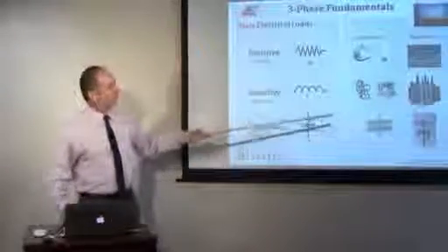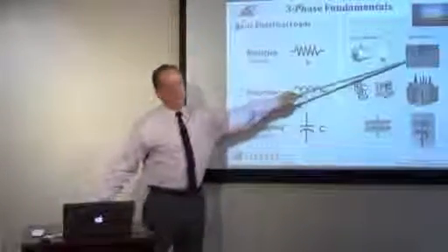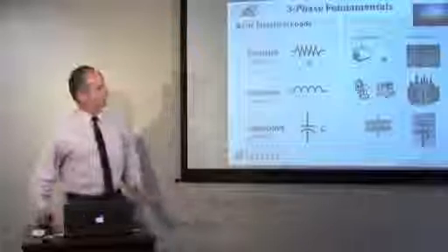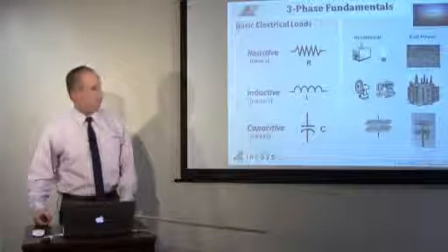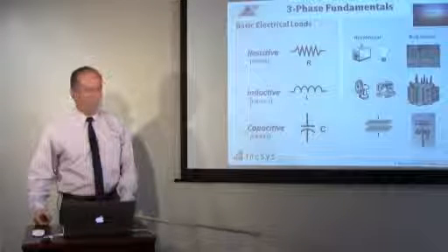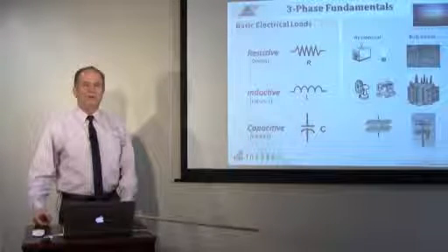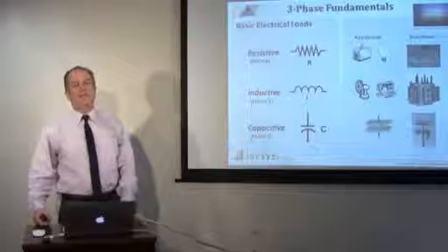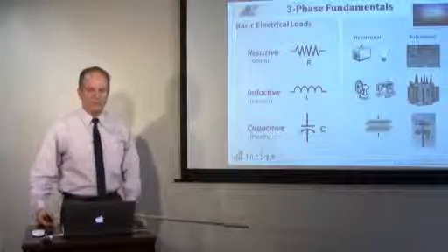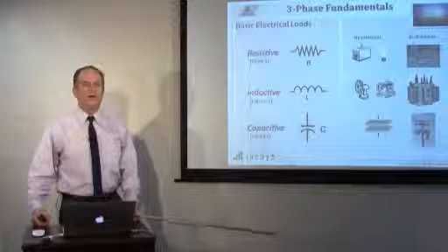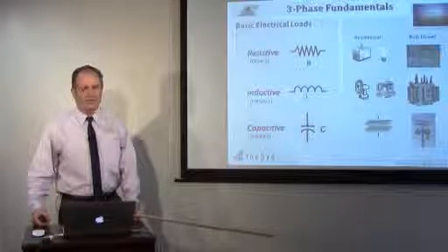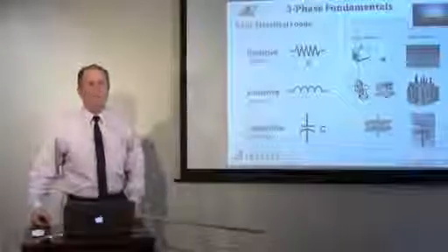But in electric power systems, this is what's called a braking resistor used at Bonneville Power, and it's just conductors going to ground. If a line were to trip and we would have excessive generation, this braking resistor would get switched onto the system right away to put load on the generator so the generators don't run very fast.